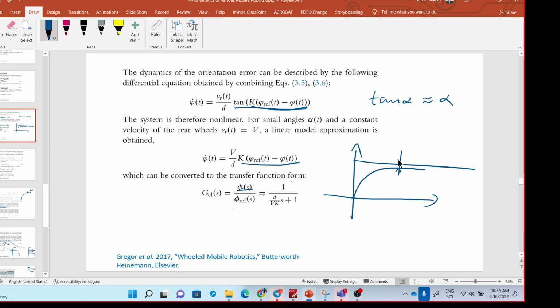From here, at what settling time, let's say at 2% of error, you want at 2%, so the time at 2% is called the settling time. So we can choose k such that you can have a desired settling time. You got the idea?